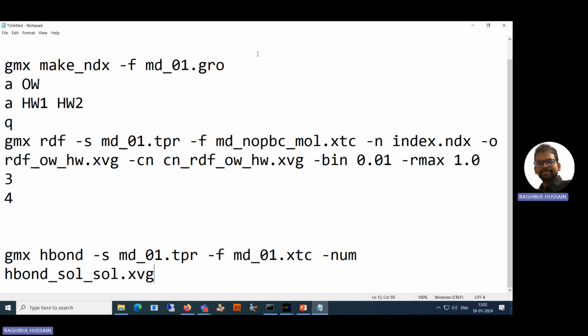Whether you compute in VMD or GROMACS, it will automatically choose the system for selection. I think for your case solvent will be the molecule, so 2,2 will be the choice. Then automatically it will compute hydrogen bonds. In GROMACS you will see three columns of data. First is time. Second is the number of hydrogen bonds, if you open that hbnum.xvg data. The third column will be the possible acceptor details: how many acceptors and donors are present, and among them which are formed. The third one is not necessary. The first two are necessary to plot the hydrogen bond data.